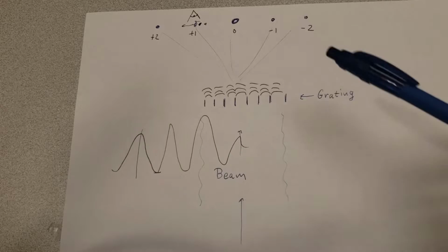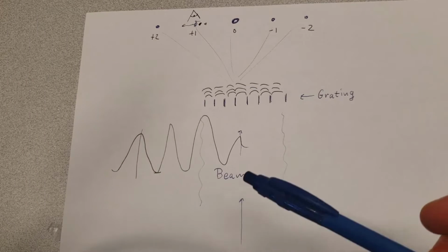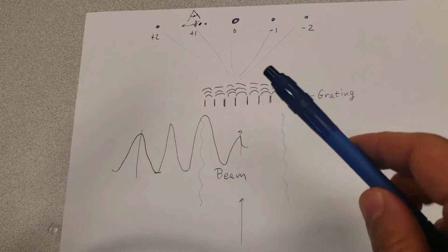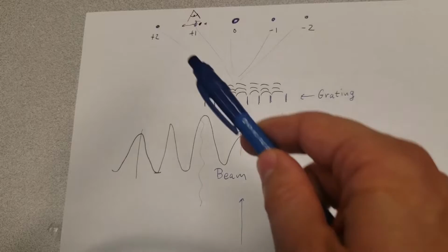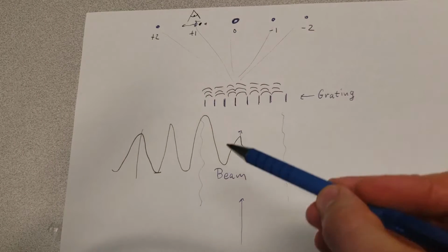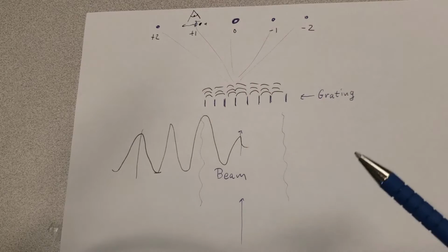In a previous video, I explained how a grating-based optical spectrum analyzer works. Essentially, just to recap very quickly, you send a beam onto an optical grating which diffracts the incoming light into different orders, and because the angle of diffraction depends on the wavelength coming in, you can split up the signal and then measure each wavelength individually.